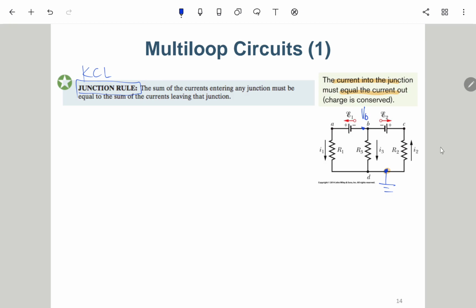And if you are a beginner to circuit theory, a student will try to define this is VA, this is VB, this is VC, and then write out Ohm's formula, and many of them are dependent. Then they try to add and subtract these formulas, and finally they make mistakes. So here, don't try to assume too many variables. For this circuit, we only need one variable.